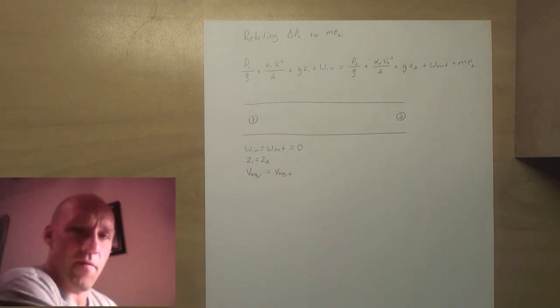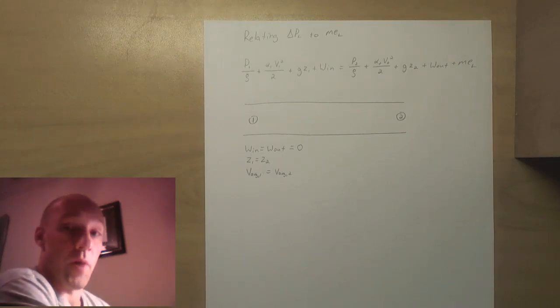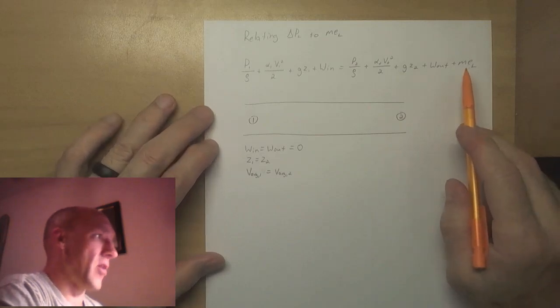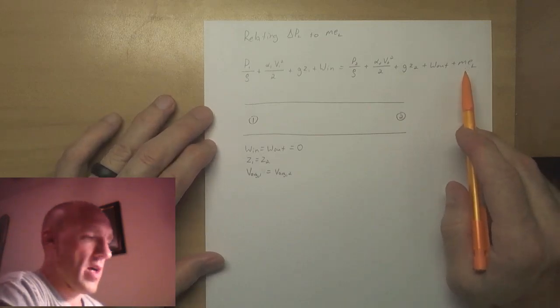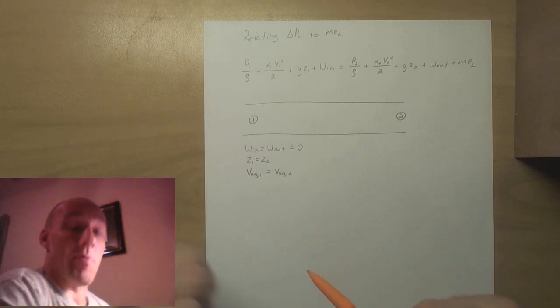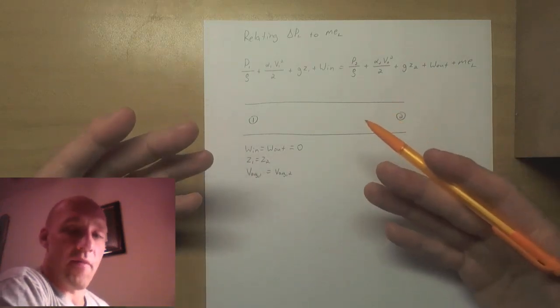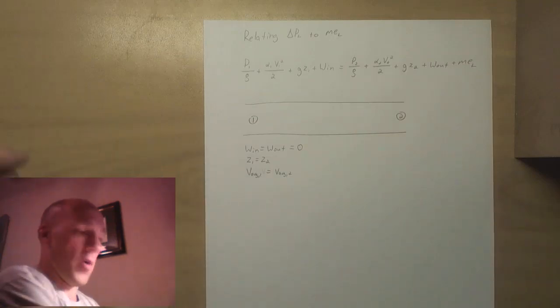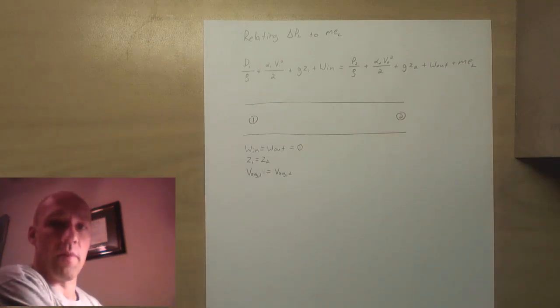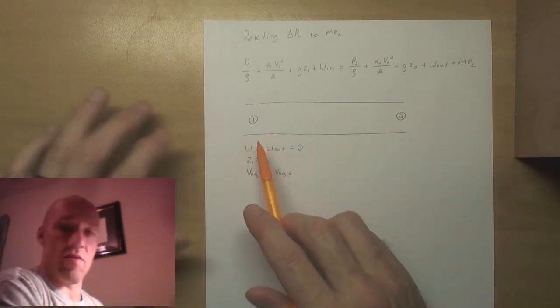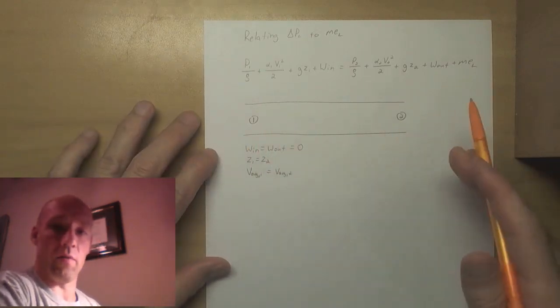Okay, so now that we have the pressure drop associated with just fluid flow in a circular tube, we'd like to relate that back to the mechanical energy that we lost. The lost mechanical energy has to be put back in order to sustain the flow, right? So we have to have a pump further upstream of the flow, that's providing mechanical energy that then is dissipated over the course of the flow.